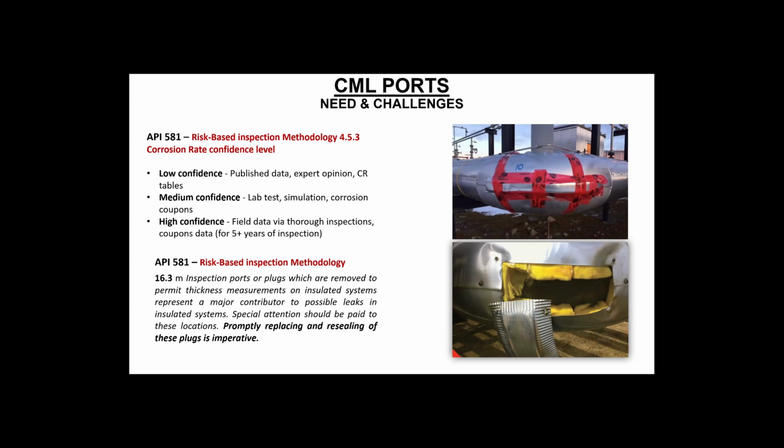So the data, which is supposed to be high confidence as per API 581, the expectation of API 581 is to have high confidence data. That's no longer going to be high confidence data because the moisture is causing the corrosion to exaggerate in certain portions. So the two bad things are happening for one same reason. That's why there is a school of thought among the end users. They used to call the inspection port a kiss of death, because they had problems in the past by having the inspection ports.